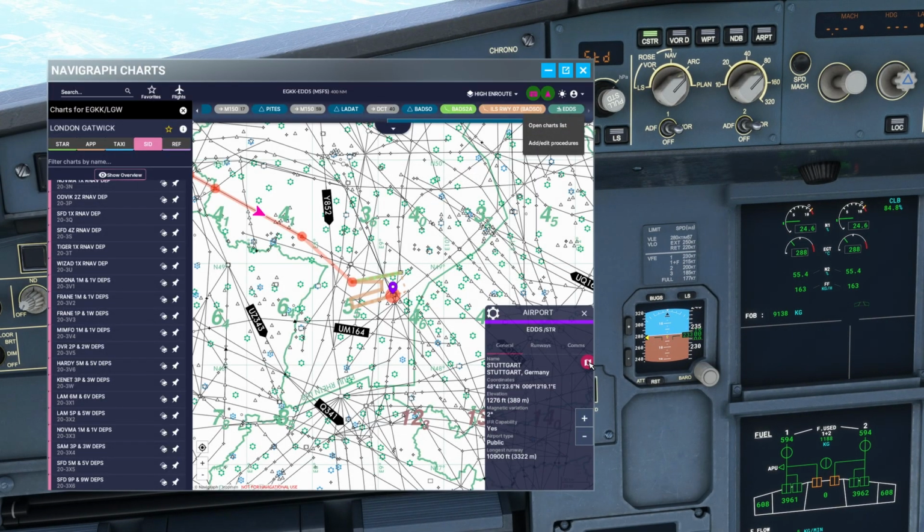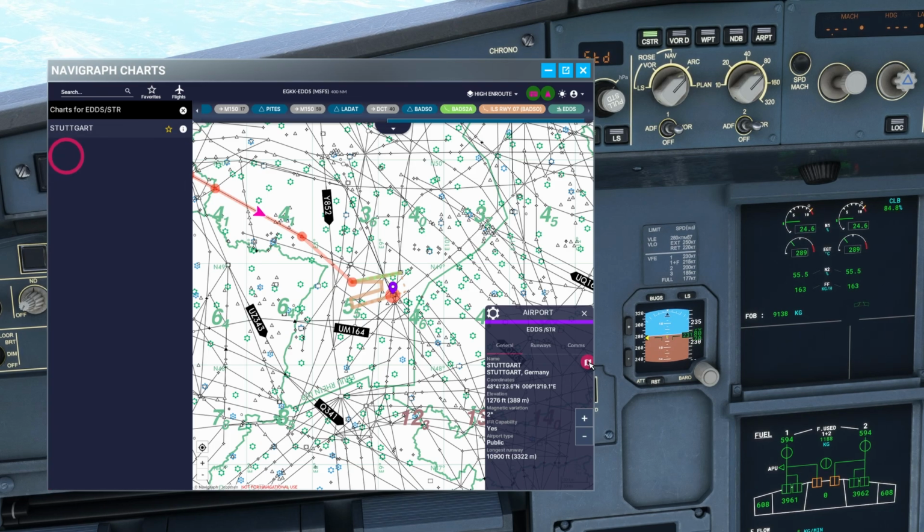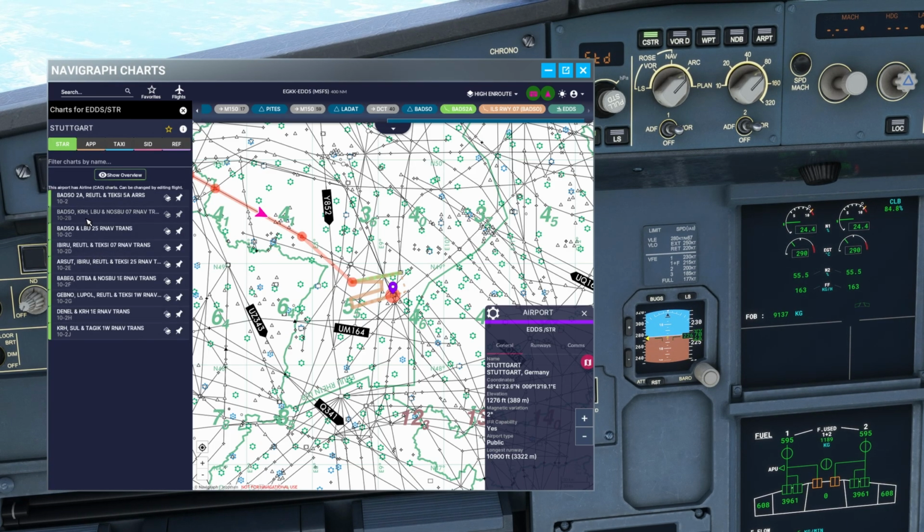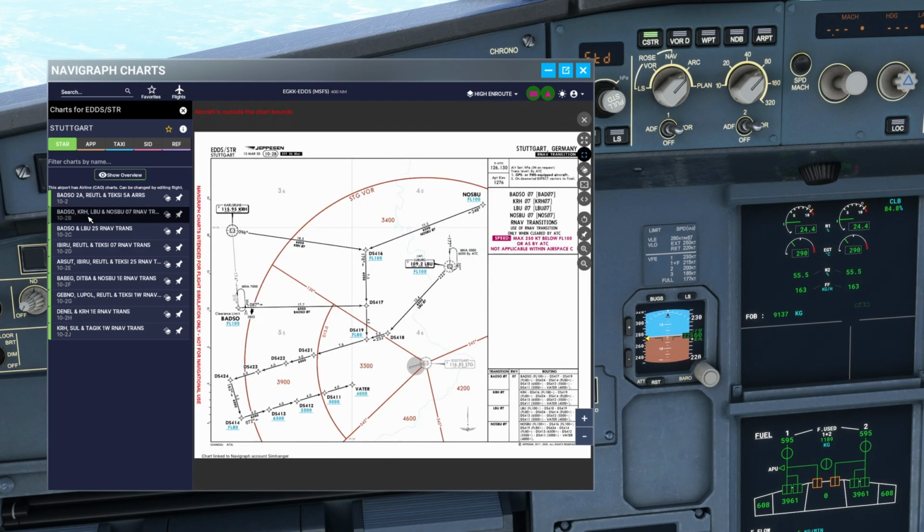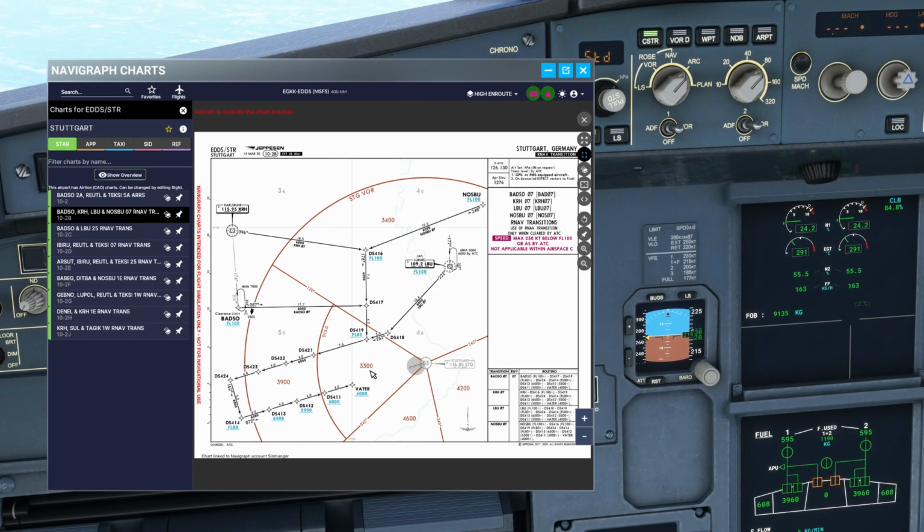Okay, so whilst the autopilot hurtles us towards 18,000 feet, this is a good opportunity just to remind us of the star and any constraints that apply. It's the BADSO 2 Alpha runway 07, and here it's showing us we need to be at 10,000 feet or flight level 100 by BADSO. Then after that we're gonna fly a defined route to Vata, and by Vata we need to be at 4,000 feet. At that point is when we will switch over to our ILS approach runway 07. But from Ladakh we need to plan on a descent to flight level 100 level by BADSO.